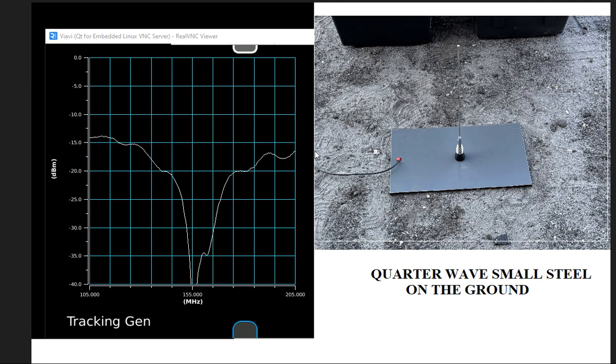Next thing I wanted to show was why you don't ever put any of these antennas on the ground, because you'll get an incredible return like this. It's even more dramatic when you put like the big aluminum plates on the ground. You'll see this return go all the way almost in, it looks like into infinity. And what it is, it is in fact true. It's not an illusion, but it doesn't work like you think it would be. Like I thought it would be.